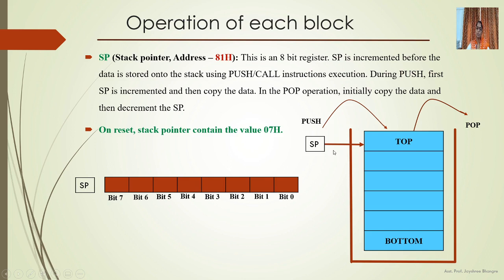So if we want to store data onto the stack, then first the stack pointer is incremented and then the data is stored into the stack. If we want to retrieve data from the stack, then first the data is taken out and then the stack pointer is decremented by 1. So upon reset, the value of the stack pointer is 07H.